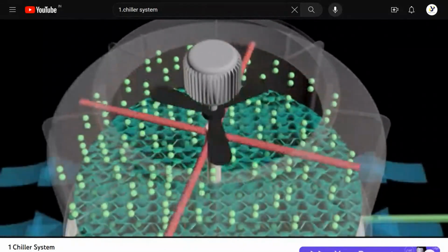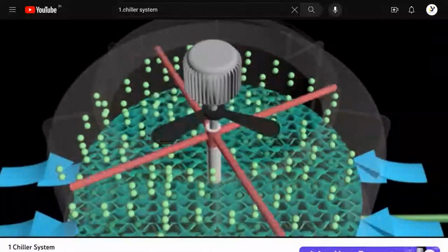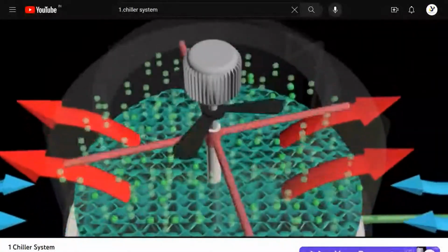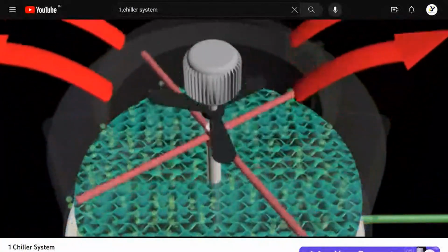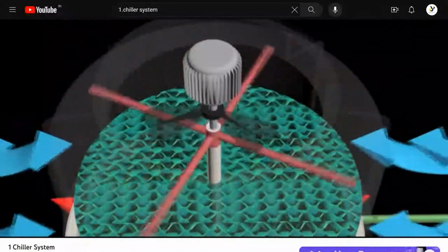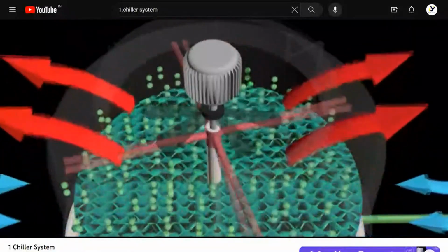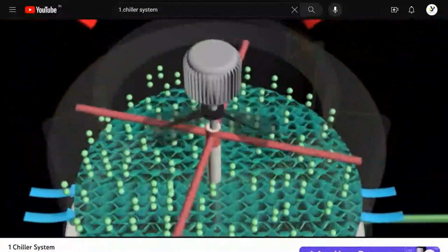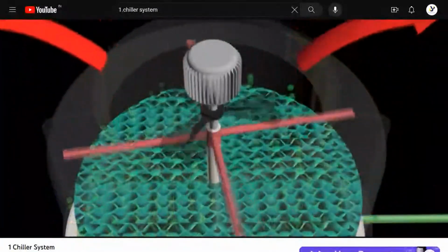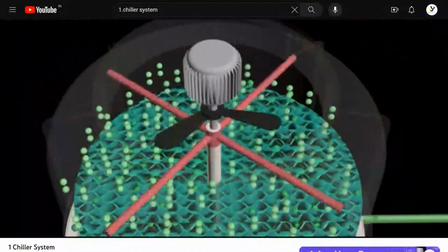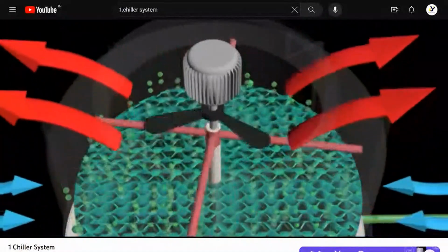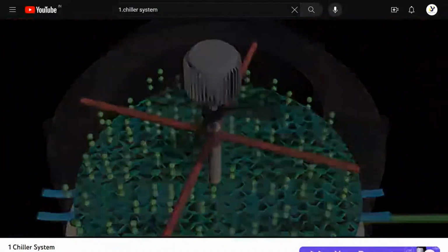Water will gush down through the fins to reduce the speed of the water going down. This can delay the time and the heat can be absorbed more effectively by the surrounding air passing through the fins. Air through the fins is forced by a rotating fan on the sprinkler blade rotated by the motor. This fan rotates with its gusts upward. This will cause the air to move from the bottom to the top of the cooling tower, opposite to the flow of the condenser water.